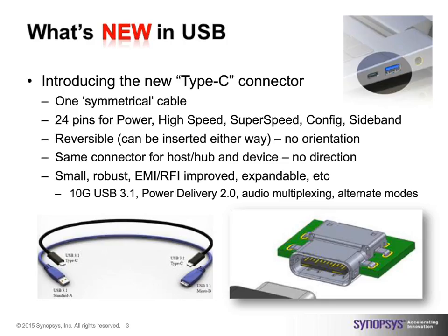It's small. It's robust. It's got improved EMI RFI performance compared to the other connectors. It's expandable. With the 24 pins that are used for power, high-speed and SuperSpeed USB configuration signals, sideband signals, you support 10G, USB 3.1, the new power delivery specification, audio multiplexing. There is something called a debug accessory, which is not yet finished, but it's in there.